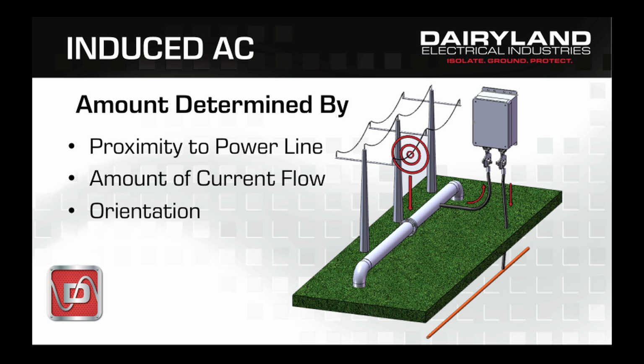The amount of AC that magnetically couples onto the pipeline is a direct function of how close you are to the overhead power line, and the amount of current that happens to be flowing through that line at any given time. You may find that the level changes dramatically over the course of the day as usage goes up and down. The orientation of the pipeline to the overhead power line may also affect the amount of AC that gets induced onto the pipeline.